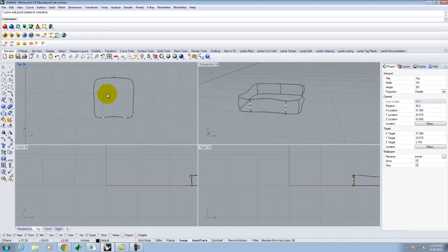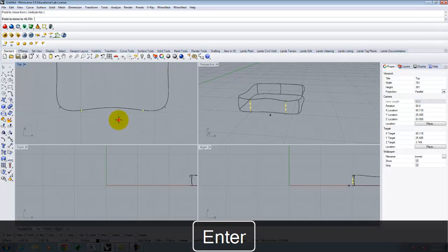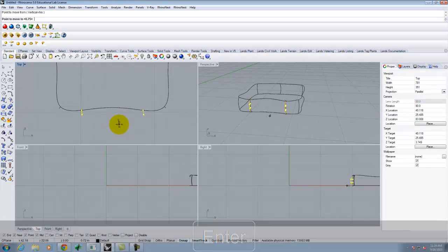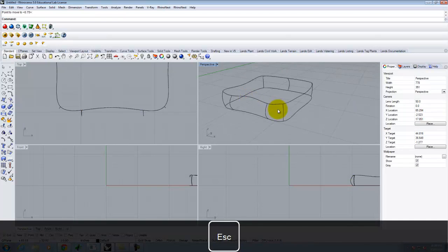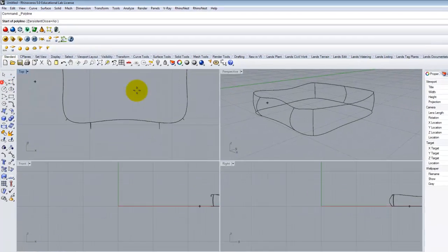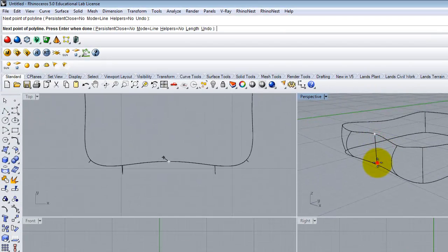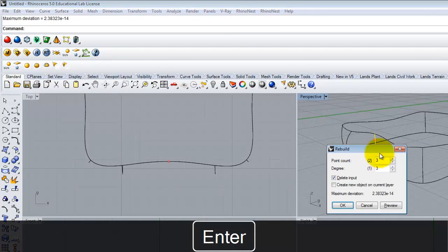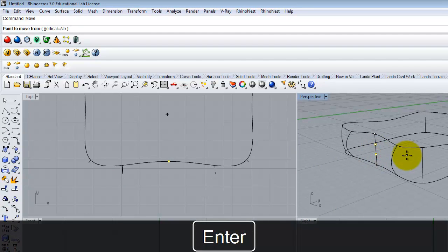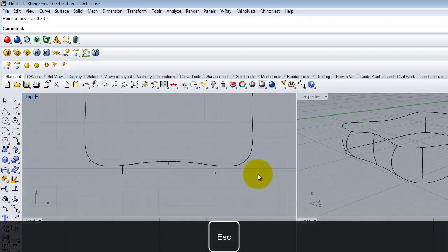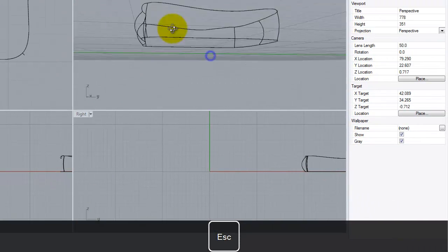Look at it in the top view here. And we're going to have those two bulge out a bit. Now, in the center, it's not going to bulge out as much, so I'm going to do another line in the center here. That goes there to there. Rebuild. So you can see this is a lot of just rebuild, edit the points. Okay? But on this line, we need it to be much less. So we'll take this point and this point. We'll move. And they're going to bulge a bit, but not too much. Something like that. Okay? So I have those starting to define nicely.